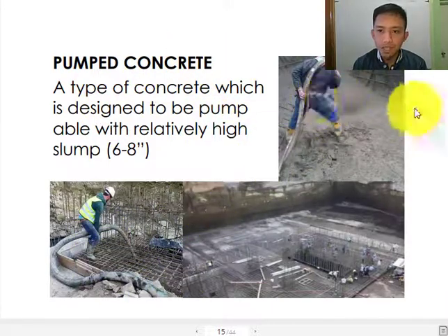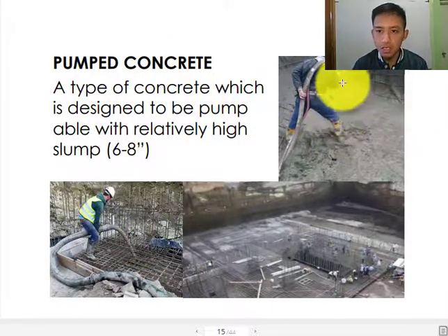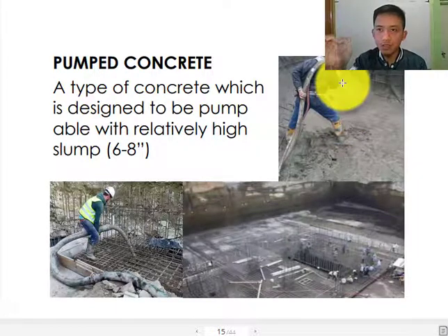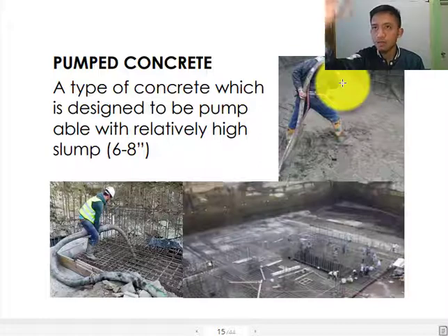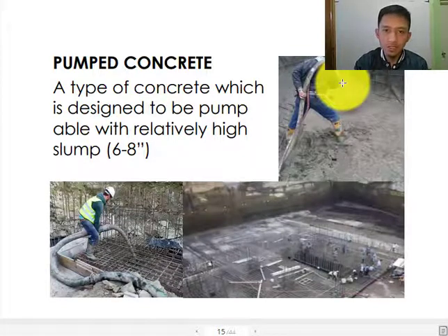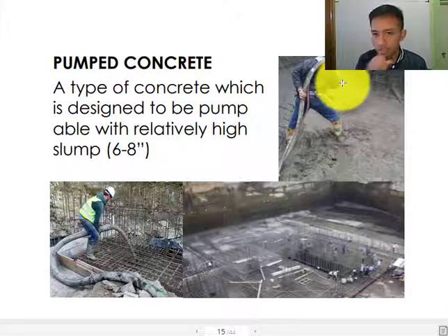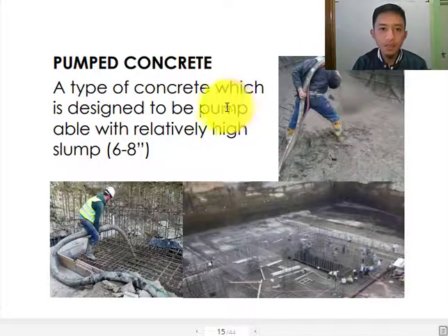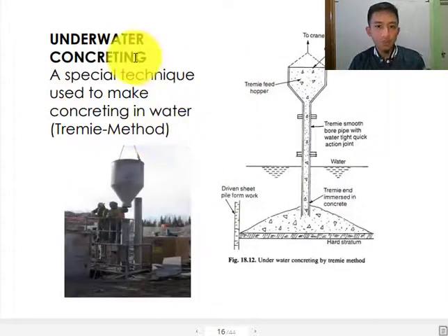Okay, shotcrete. This one is shotcreting. You say shotcrete, you are going to paste this concrete mix on a vertical wall, or on the edge of a mountain. That is shotcreting. So you really need to have also a concrete which is consistent enough for that to flow, or for that to be pumped on a vertical wall.